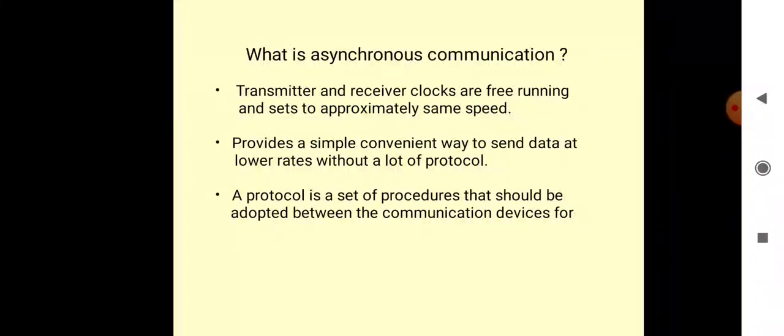The advantage of this parallel transmission is that speed will be more, but the disadvantage is that parallel transmission requires n communication lines to transmit the n data bits. That's why it is very expensive. For each and every single bit, certain paths should be maintained. So parallel transmission is used for only shorter distance communication.